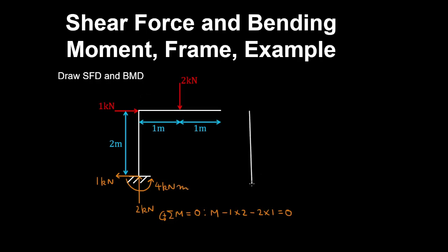And now let's first draw in our shear force diagram. And I'll remind you of the convention that we use when we cut the beam and the column. So I'll draw those in quickly. And we rotate this positive sign convention for the beam anti-clockwise to get our positive sign convention for the column. So if we cut the beam from right to left, we use this convention.